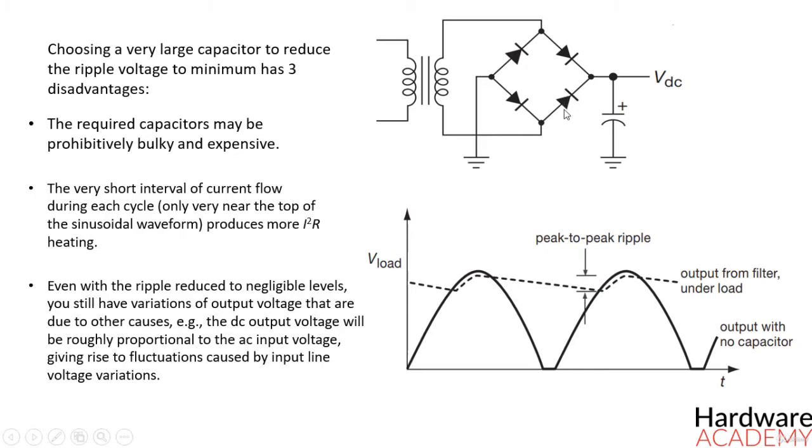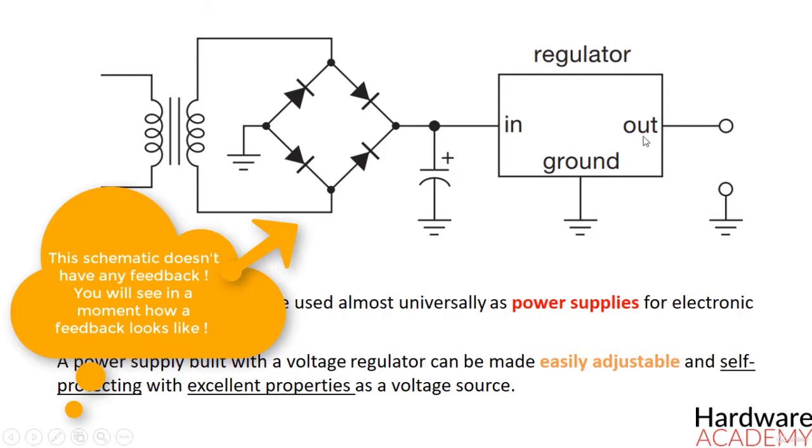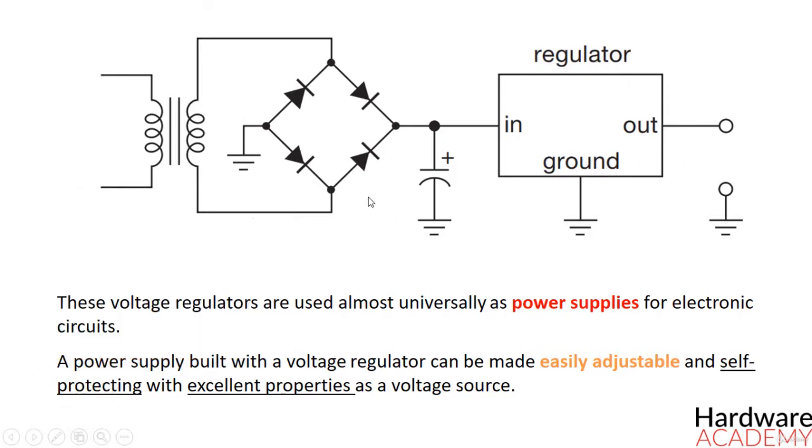A better approach to power supply design is to use enough capacitance to reduce ripple to low levels, perhaps 10% of the DC voltage, then use an active feedback circuit to eliminate the remaining ripple. Such a feedback circuit looks at the output, making changes in a controllable series resistor as necessary to keep the output voltage constant. This is known as a linear regulated DC power supply.